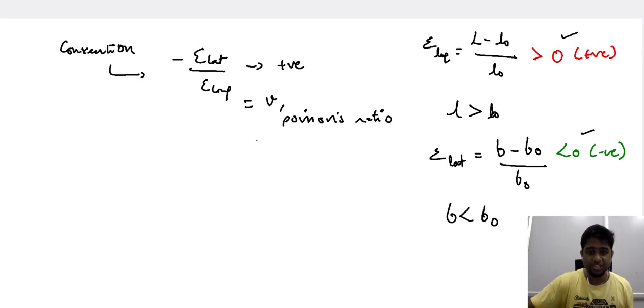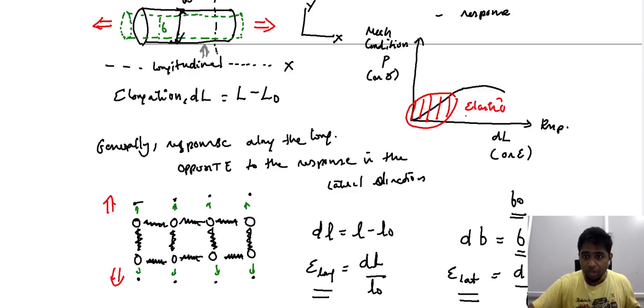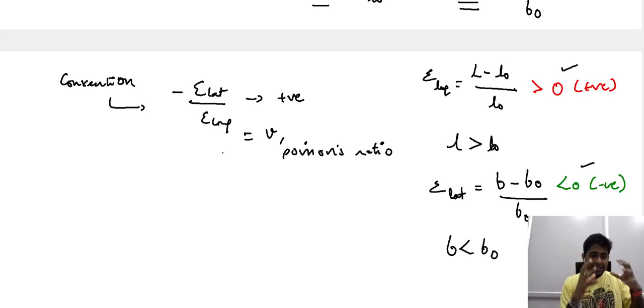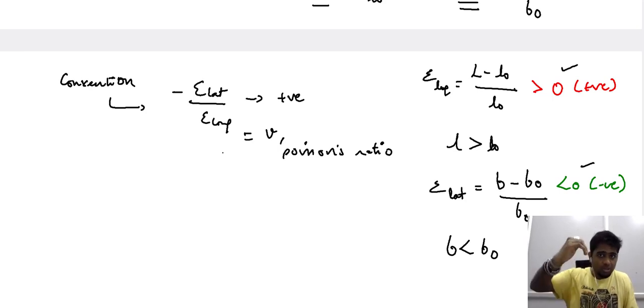Now what we have essentially done is, using the Poisson's ratio, we have introduced a parameter that can describe both the longitudinal strain and also the lateral strain. So initially when we were discussing this particular plot here, we restricted ourselves to the longitudinal response alone. Now we have a parameter that encompasses both lateral strain and longitudinal strain. So we began with two specific restrictions. One restriction is associated with the response that we consider, that is we have been focusing largely on the longitudinal response alone, so we wanted to relax that assumption.